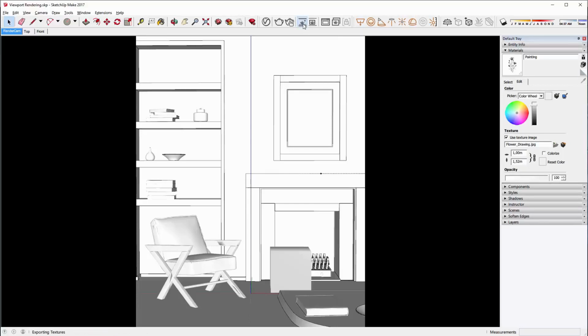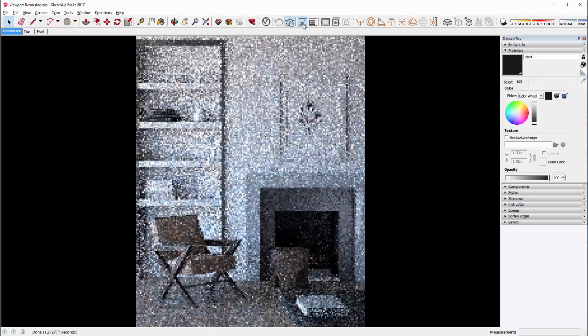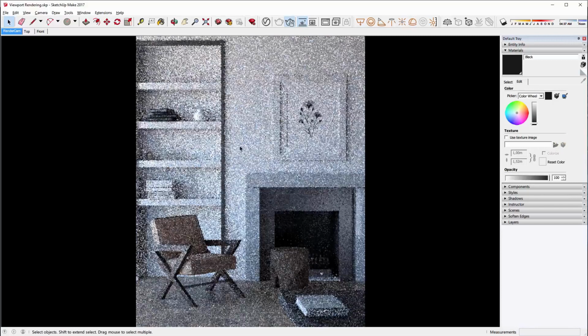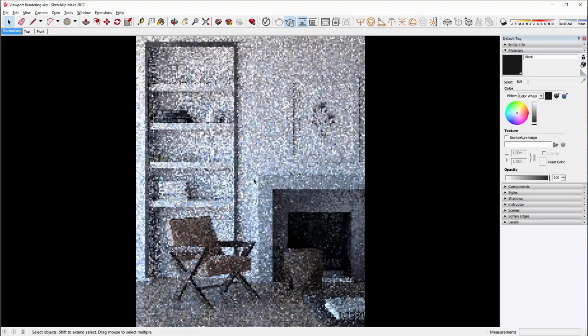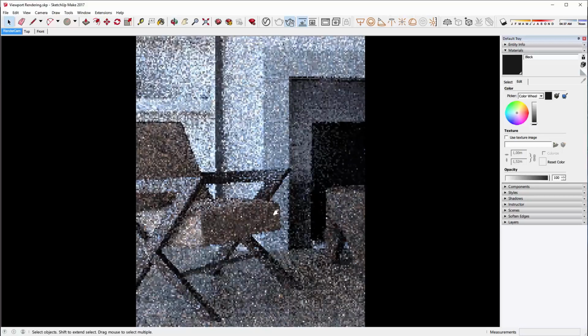You'll be able to, in a few seconds, V-Ray is now exporting the scene. And there you go. The render has started. And now if I move around, the render will update basically instantly. I can rotate the camera, zoom in and out and pan, and do basically everything as if I'm in the viewport itself.